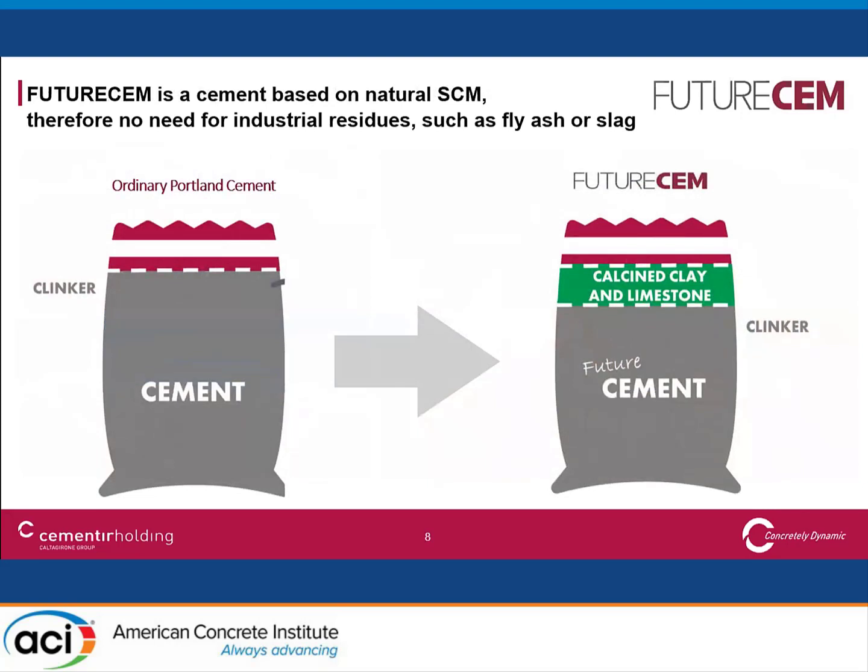our commercial drawing of this new cement, which replaces the typical cement used in Denmark, which is an OPC with 5% limestone filler, 5% gypsum, with a cement where a significant part of the clinker is substituted by calcined clay and limestone, up to the 35% substitution, which is allowed by the European cement standard.